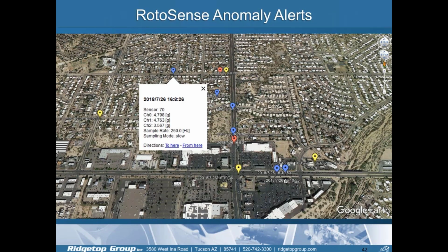The RSDK is comprised of one or more RotoSense units, the Sentinel Gateway and the Sentinel MotionView software application. And then another unique application that I thought I'd throw in: you can see here different types of GPS locations, and this was using an RSDK on a particular vehicle as we were driving around near our office here in Tucson detecting potholes. Interestingly enough, after we did that, the city sent out maintenance crews and started fixing some of these. If anyone's been in Tucson, some of the potholes out here can get pretty bad, but you can see here the red ones are pretty severe, the blue are minor, and the yellow are intermediate, according to the acceleration we were observing there.